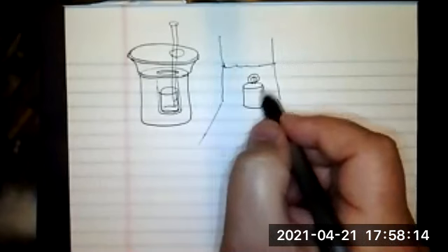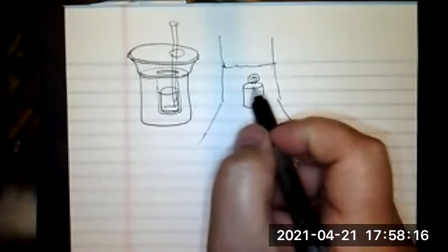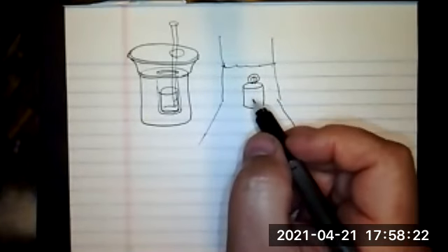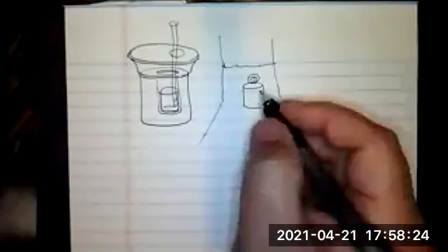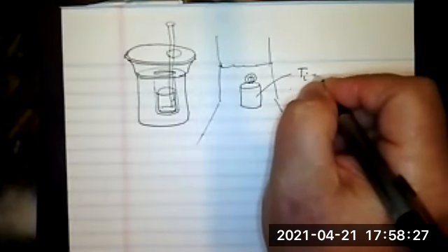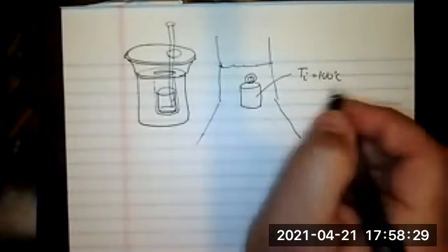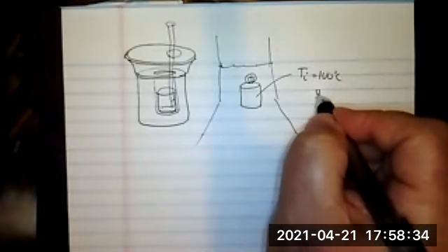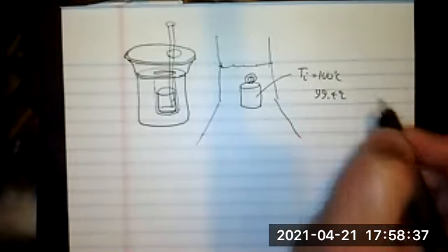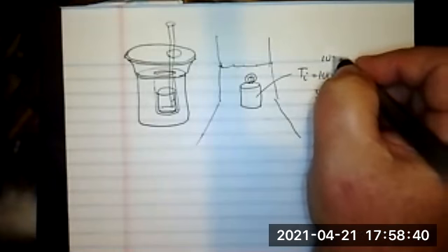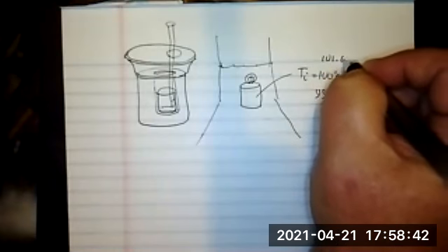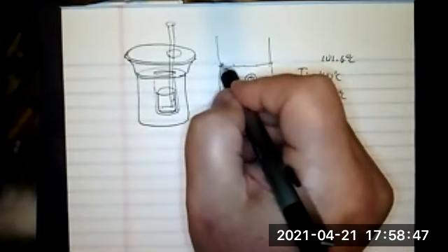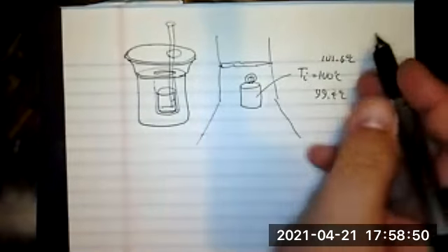Since it's a metal, it's a conductor, so it gains the heat of the surroundings rather quickly. If you leave it submerged in boiling hot water for 5 or 6 minutes, then it will have an initial temperature of 100 degrees Celsius. Of course, you could also correct for that, because low atmospheric pressure might allow it to be at, say, 99.4 degrees Celsius, or high atmospheric pressure might not allow the boiling to occur until 101.6 degrees Celsius. But you'd have a thermometer in it to actually check that temperature.